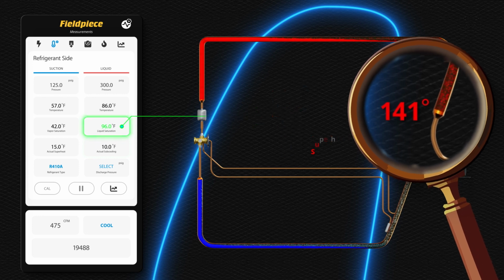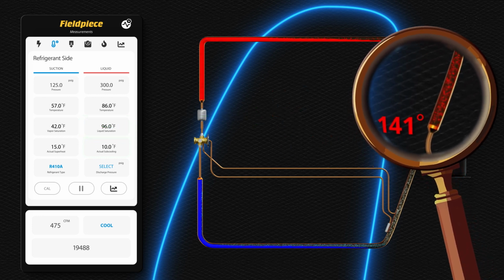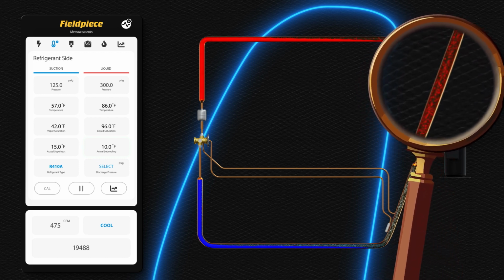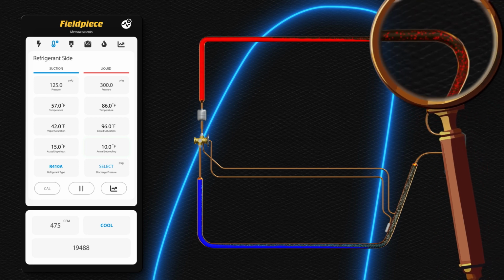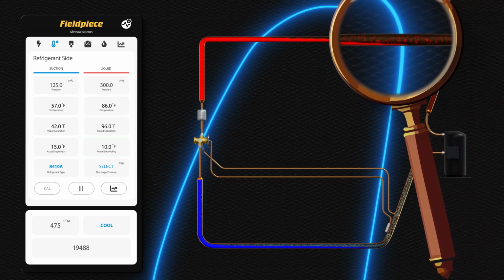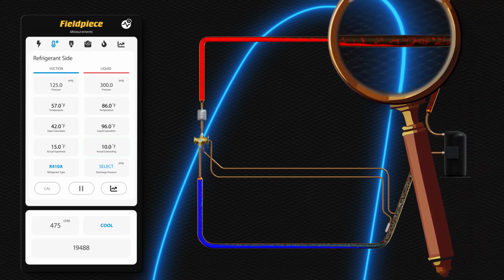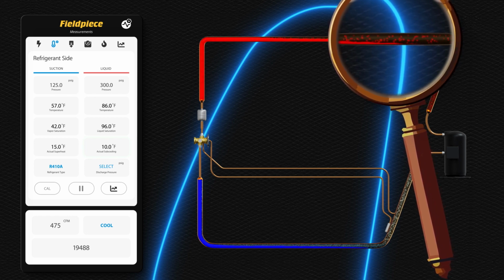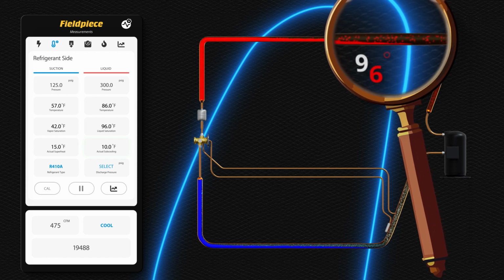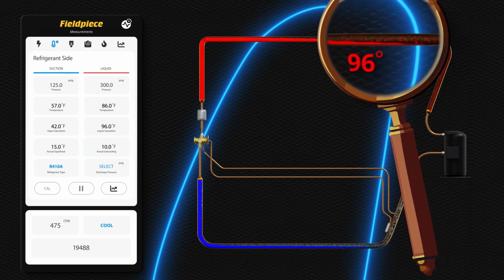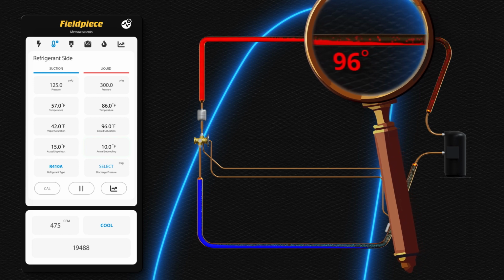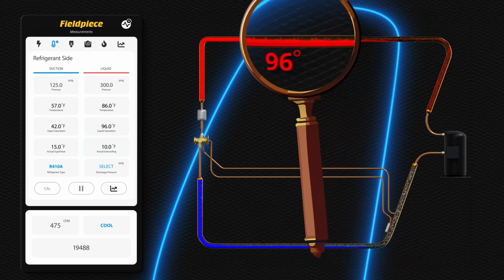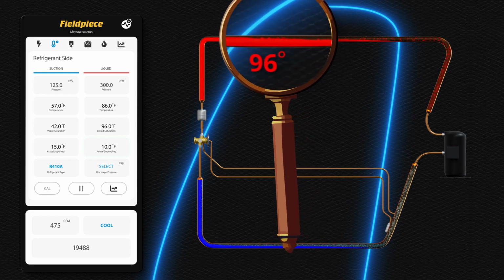As the refrigerant travels through the discharge gas line into the circuits of the condenser, the first function of the condenser coil is to de-superheat the refrigerant. Just before the refrigerant crosses a saturation curve, the refrigerant will be above the saturated condensing temperature. When the refrigerant crosses the saturation curve, the temperature of the saturated refrigerant will be 96 degrees. As the refrigerant travels through the condenser coil, rejecting more heat, the vapor condenses into a liquid and does so without a change in refrigerant temperature.